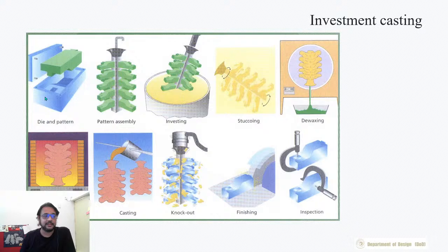So first, as you saw, there was an aluminum die or a metal die in which wax was poured, and individual parts, which would later be transformed into metal, were formed. These were connected into a wax tree, like this shape over here. These were then coated with something called investment, which is a slurry that would later become ceramic, and after subsequent coatings you would, at the end, coat it with a powder to make this outer layer of ceramic very strong.